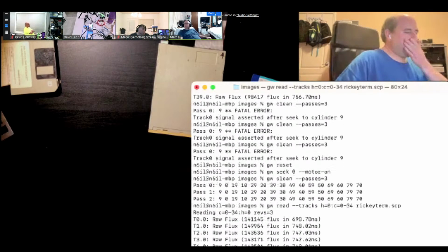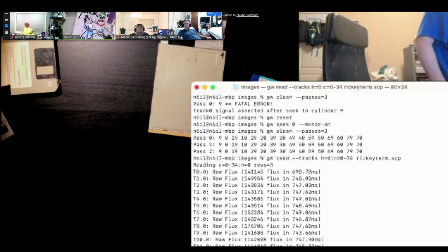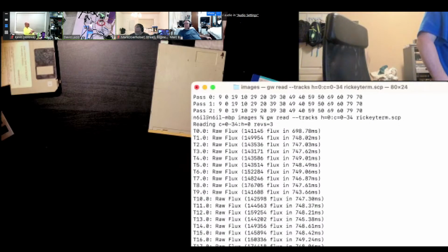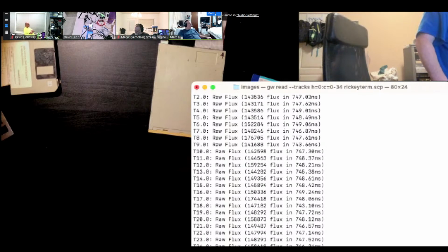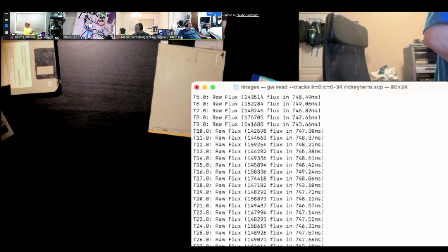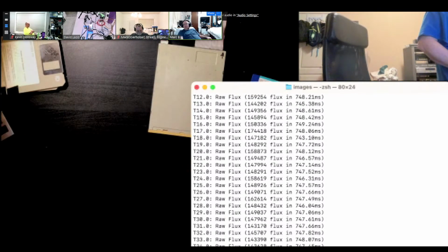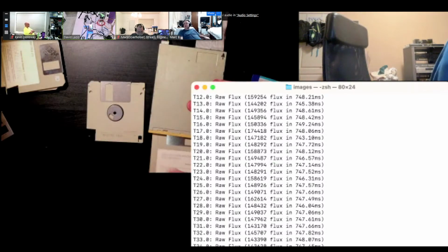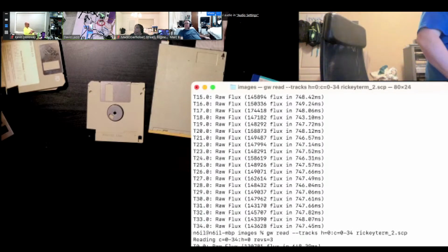Which is why some people will cut that trace on a 5.25, and they'll put a switch on the front of the 5.25 so they can manually force the drive to be high density or double, to adjust the speed. Yep. And there's some drives, like the high density drive I have, you can put a jumper on it to lock it at 300. Yes. The 300 RPM is only used when it's in double density mode. Right.